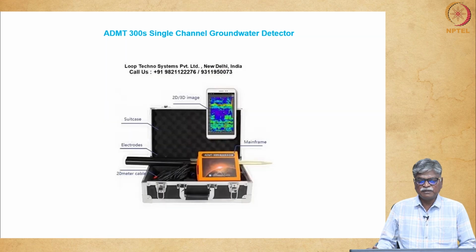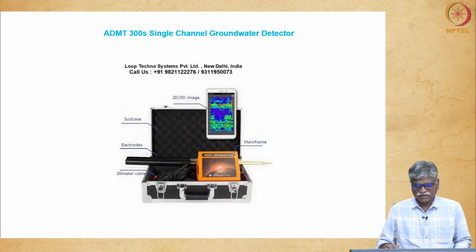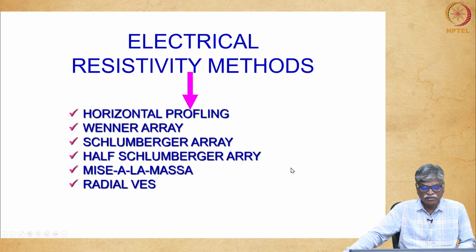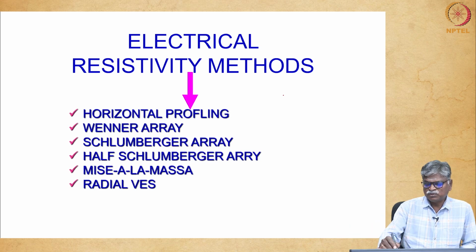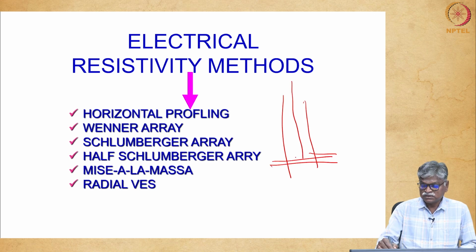If you use multiple channels, you will get 3D imaging. With single channel, you get this type of groundwater information figures. This miscellaneous survey we can do where limestone is there, in limestone areas. How to do this miscellaneous survey? Suppose this is your borewell, where you got the cavity. You put one electrode, C1, here, and one electrode should be